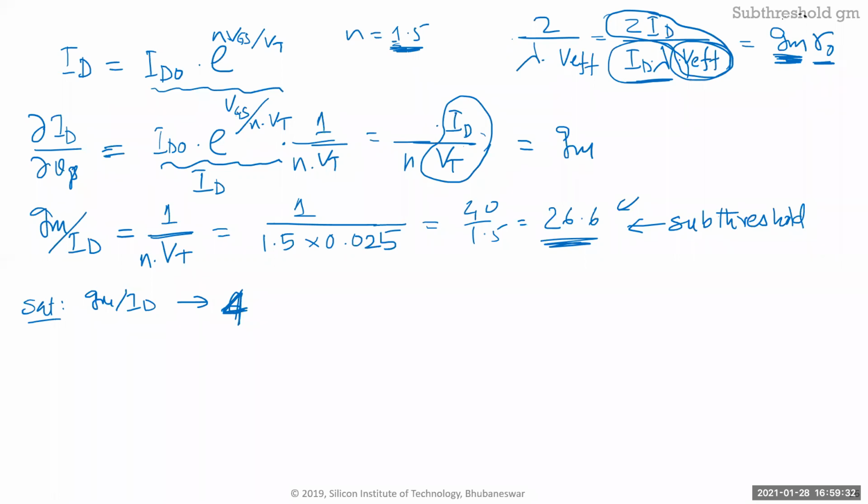So you'll see when you're doing op-amp designs and you want to optimize them, the input pair of your op-amp should always be in deep subthreshold if you can afford it. What I mean by afford it is if you don't have speed issues of driving it or area issues, you always drive it into subthreshold. And it still boggles my mind that a lot of designers just put it in threshold. So you're 4 times less efficient, which is huge. In low power circuits, that's huge.